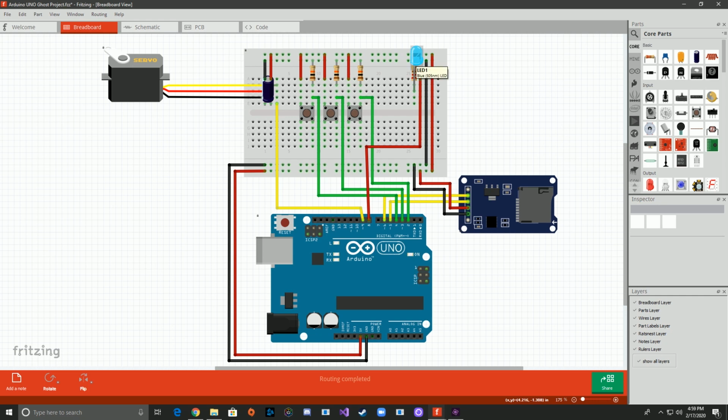So we've got pin 8 here, which is providing power to the LED whenever one of these buttons is pressed. And we'll go over the code of how it does that later. But behind that, we have the 220 ohm resistor with the gold ring facing out. And that pretty much sums it up for this top half. Now we're going to come down to the serial module and the bottom half.